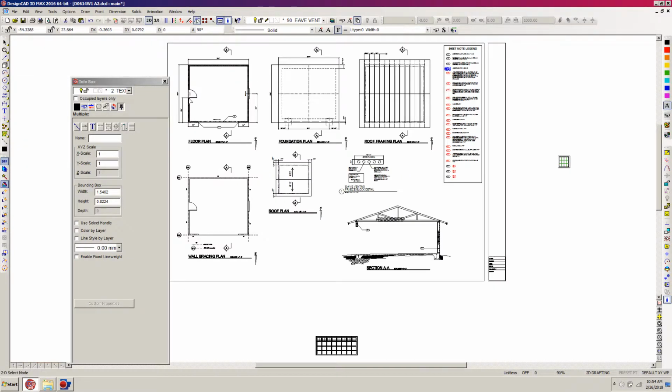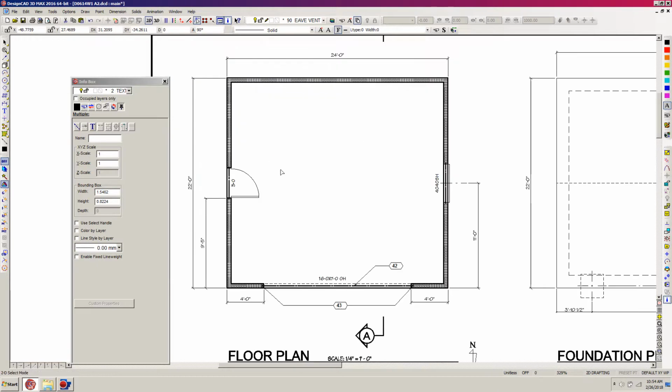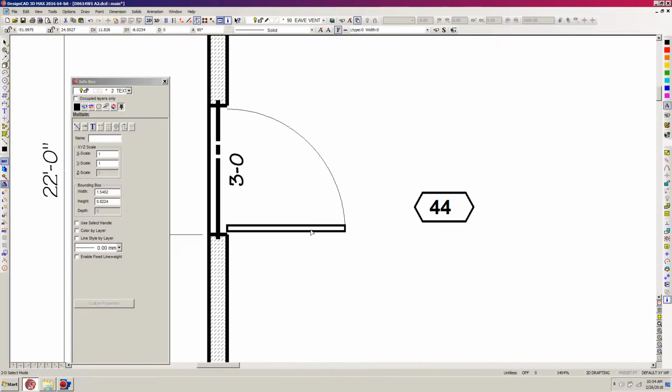Control W. And so now what we're going to indicate is these additional two headers. So I'm going to hit Z for zoom and zoom up on the floor plan here and hit N to duplicate. And here I'm going to position the 44 box, and N, and I'm going to position the other one over here. And now I'm going to zoom up on this guy by hitting Z, arrow command, again greater than, H for orthogonal mode, and then K, and hit my scroll button to initiate the command, Control R to regenerate.